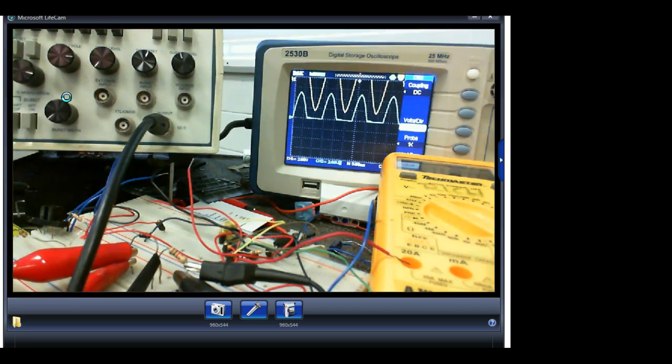So everybody okay? That's pretty straightforward. What we're doing now is we're taking AC and converting it into what we call what? Pulsating DC. And you still get an average. Now your DC meter works great over here because it's giving you the what? It's giving you that DC average that we're calculating. Everybody okay? Okay guys, take a break. A few minutes.